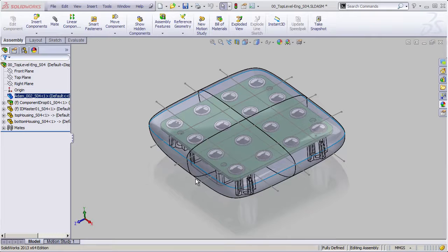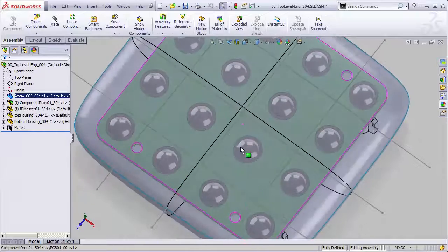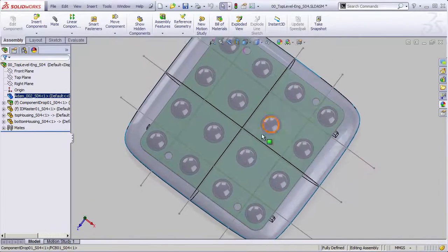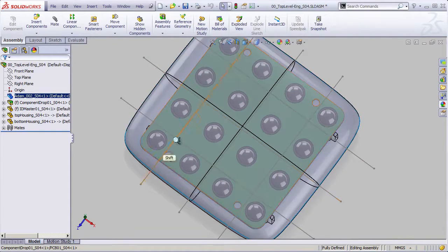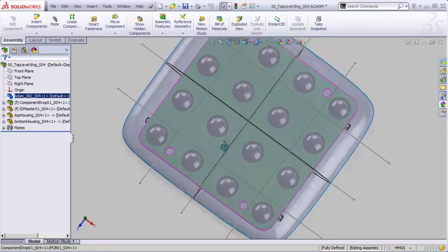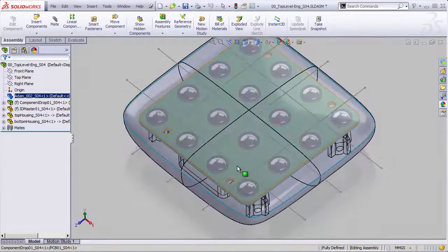So here we are back over in engineering world. I've put on my Josh hat and now I'm working here in the mechanical engineering assembly. And you can see that we've had to make some changes to this. The circuit board, for example, has had to grow a little bit in order to put the proper number of sensors under each button. And also we've moved the screw bosses in between some of those just because there was no room for them in the corners. Otherwise we were going to have to grow the unit too much.